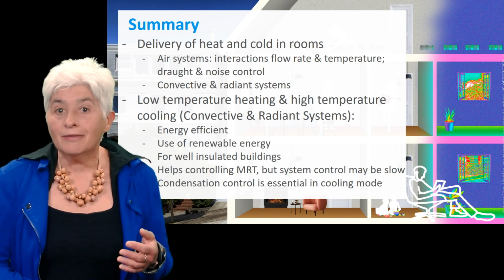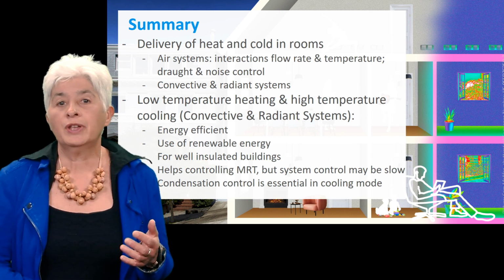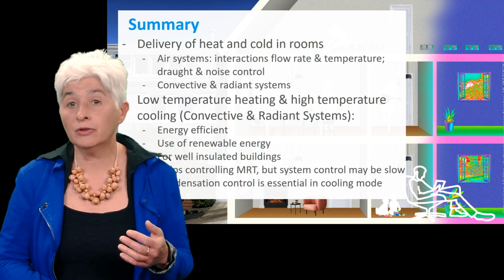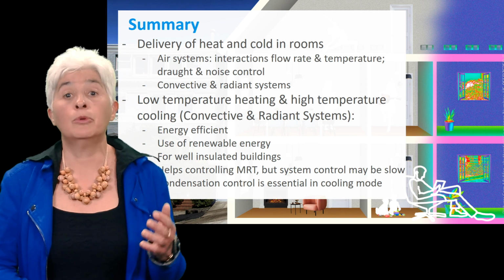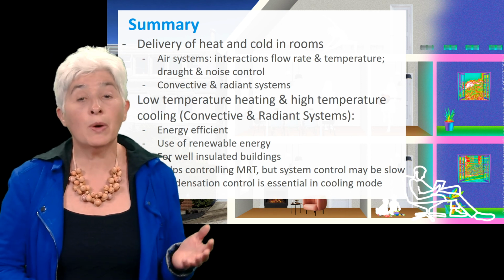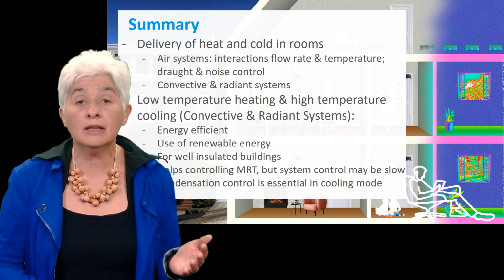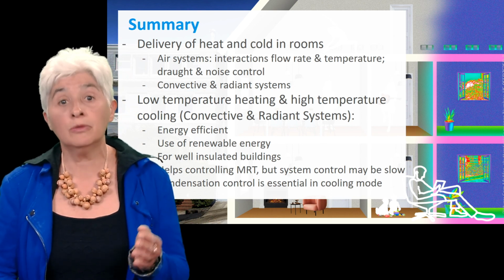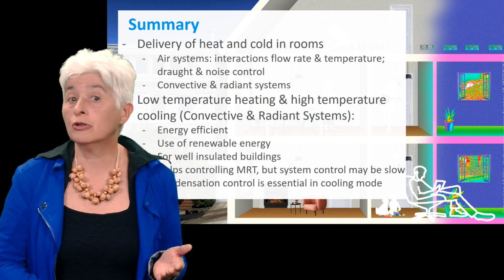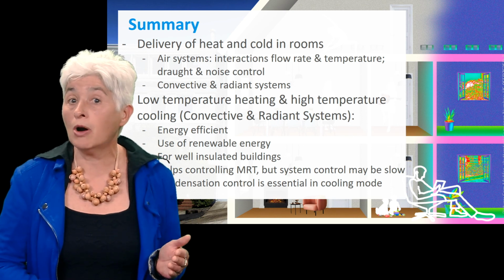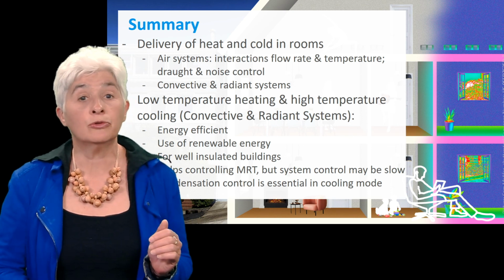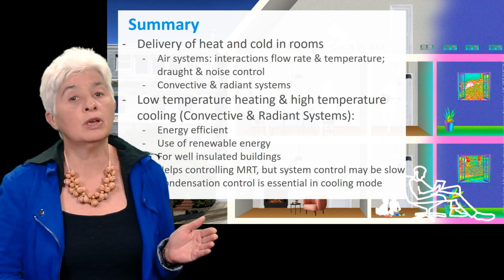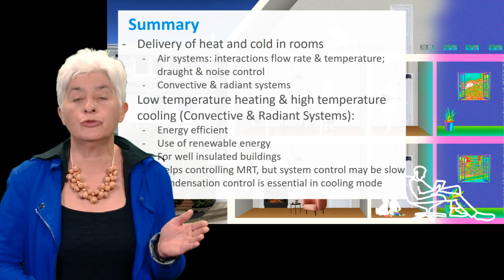When using convective and radiant surfaces, low temperature heating and high temperature cooling are energy efficient and allow for the use of renewable resources. However, well-insulated buildings are needed when using such systems, otherwise the MRT may not ensure comfort. In cooling mode, attention must be paid to acoustic and, even more important, to condensation control. Floor systems are reacting slowly to changes, which may be annoying for residents if not used to it.